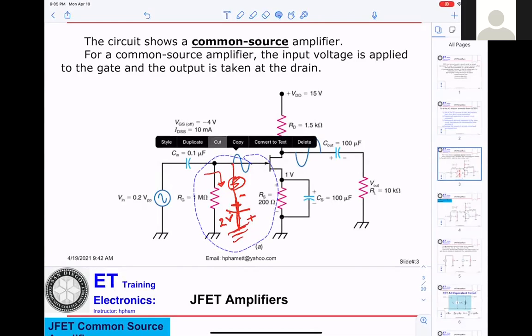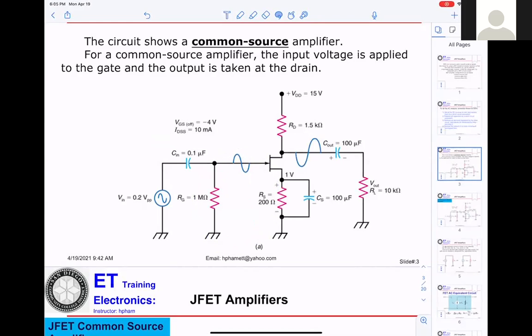Yeah, go ahead. Isn't it true that the C and the R actually do have a cutoff frequency, but the assumption is that the frequency of the source is so high that it's well above the cutoff frequency, so that you can treat the capacitor as a short circuit? If the frequency of the source was, say, 10 hertz, then that capacitor would not look like a short circuit.